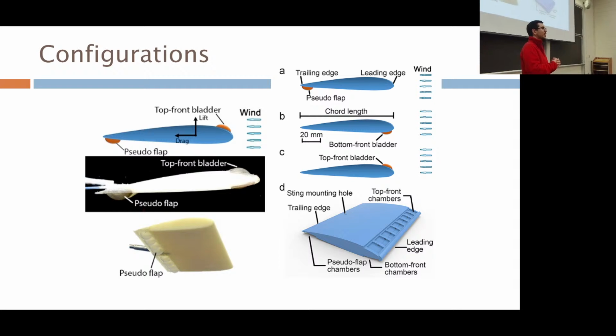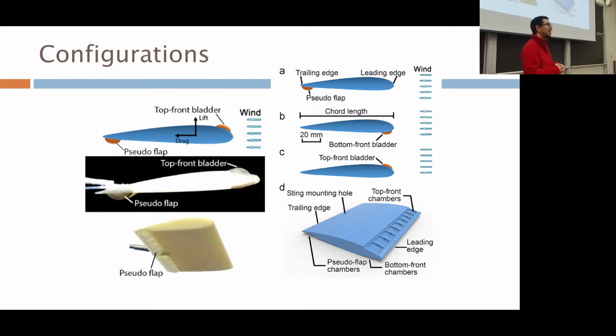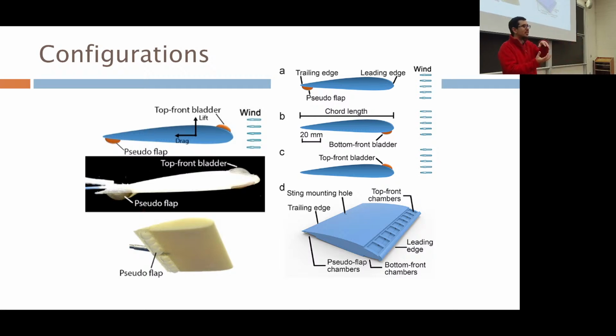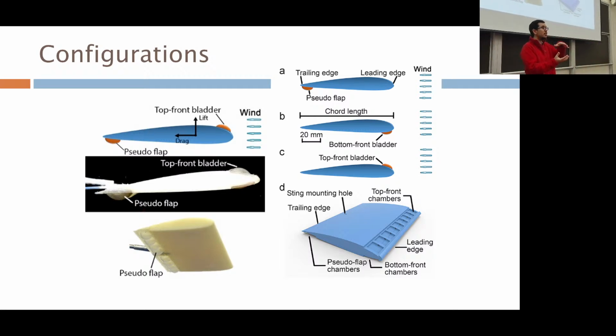Trailing edge. Okay, why? Okay, probably just prolong the boundary there. Yeah, so if you increase the length of the chord, you're going to get more lift, right? That's a good observation. On top? Okay, where on top? Like, at the apex right here. Okay, so now you're essentially making it thicker. Yeah, so you can definitely tell that in some designs that would be advantageous, especially at lower Reynolds numbers.